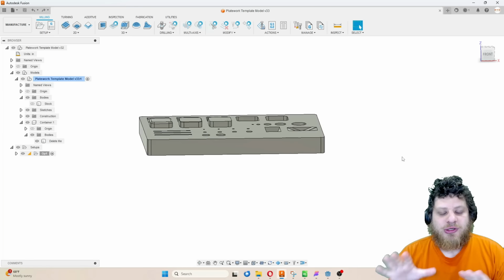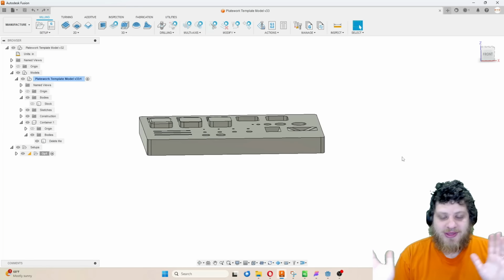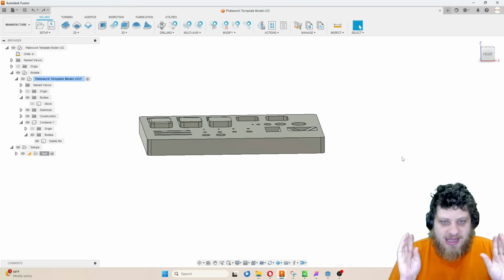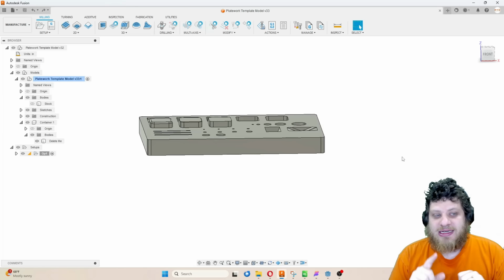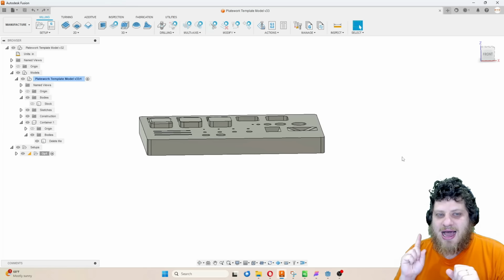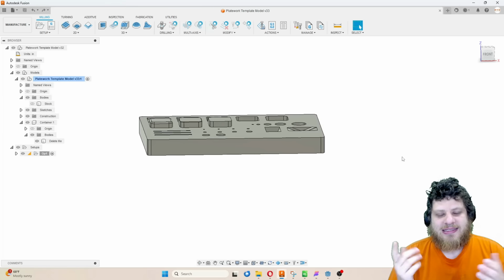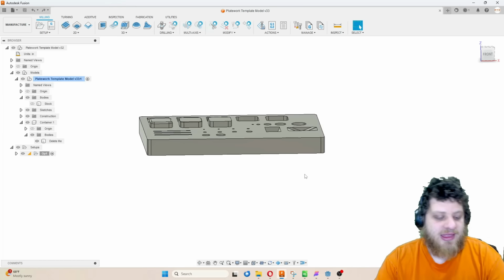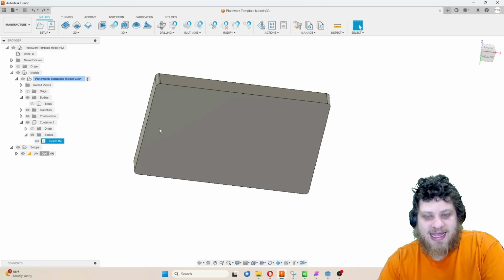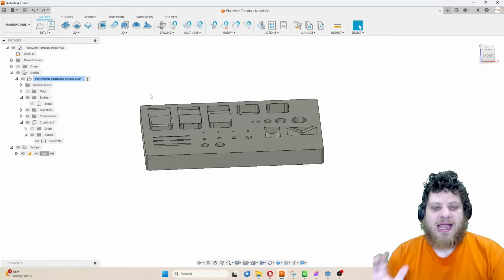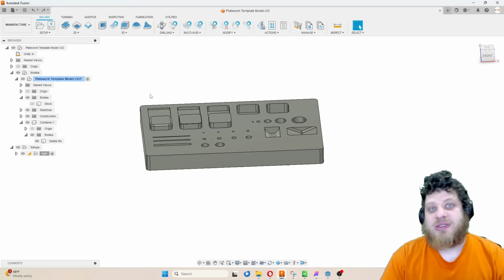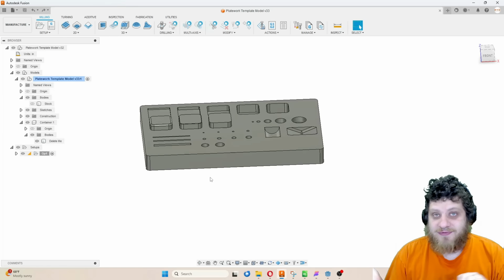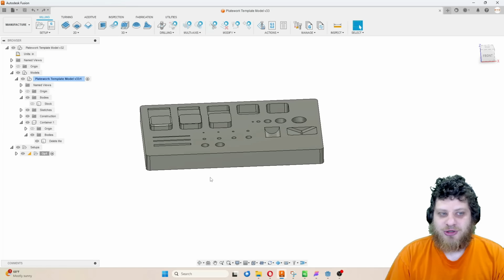Now, I have a whole YouTube video on the superglue method. You should probably go watch that for this to make the most sense. But a lot of the times when I am doing these superglue parts, I am doing them as essentially a one-op part. Most of the time, I start by facing the backside of the material, and then I glue that clean-faced material down directly to the fixture. And the fixture, I again face right before I put the material down.